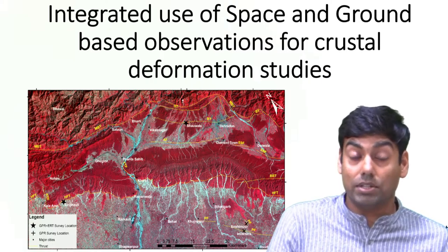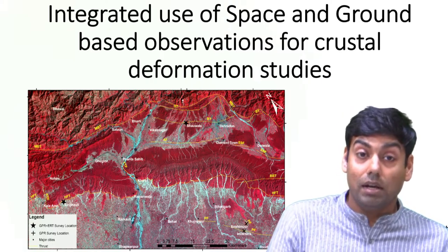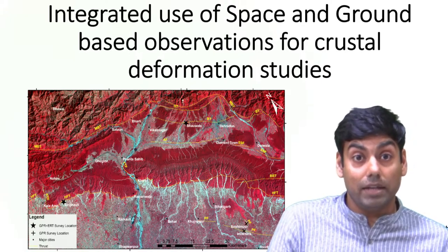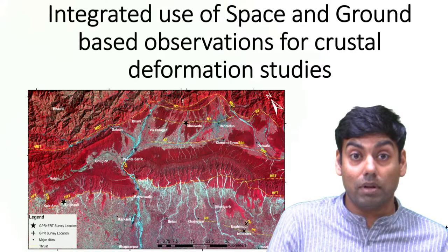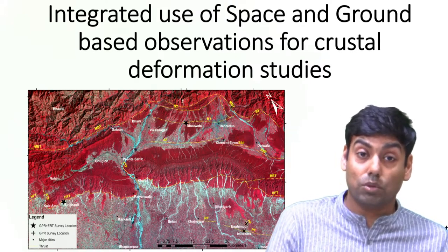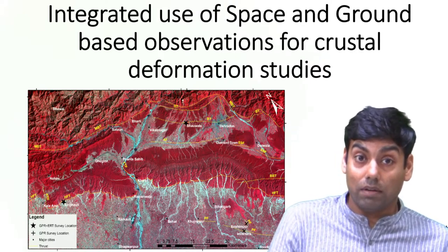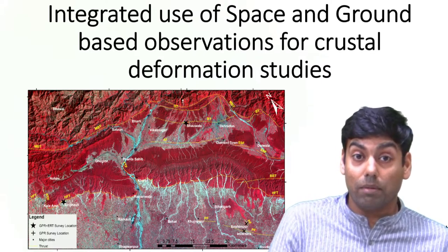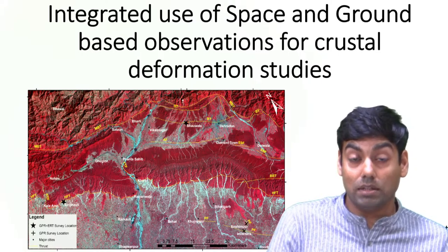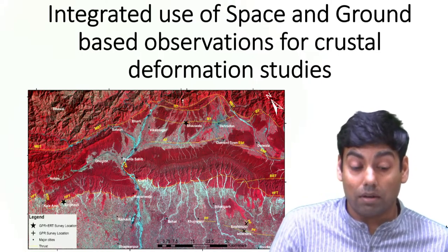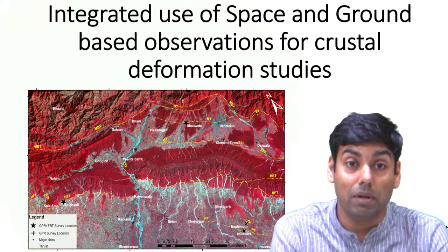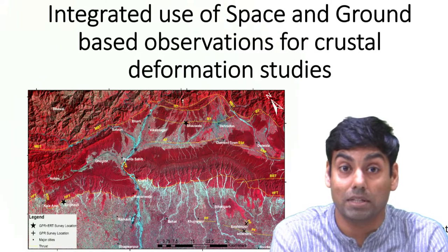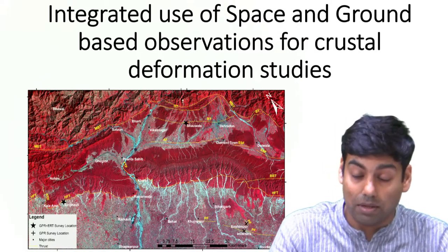Active fault characterization becomes very essential, because when there is a great earthquake, it can reactivate all the active faults available nearby. And if the population is big in those areas, it can have a huge impact on society. That's why my today's lecture will be focused on how we can efficiently use space and ground-based techniques for crustal deformation study.